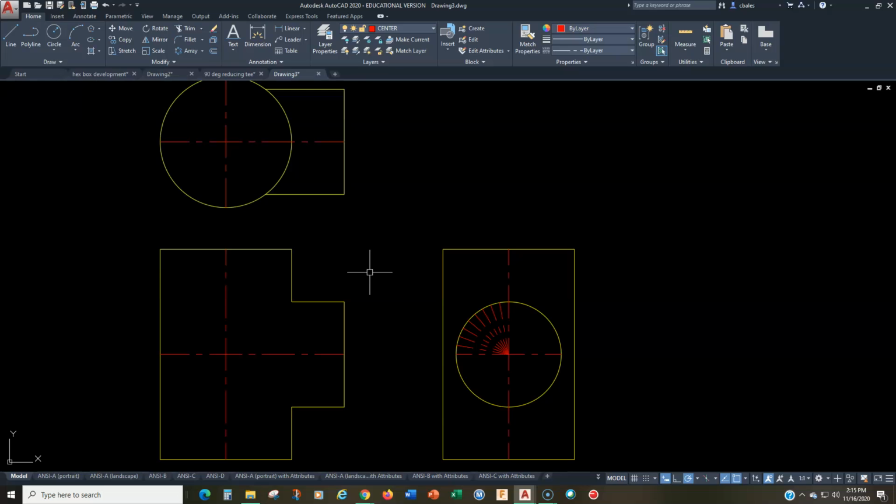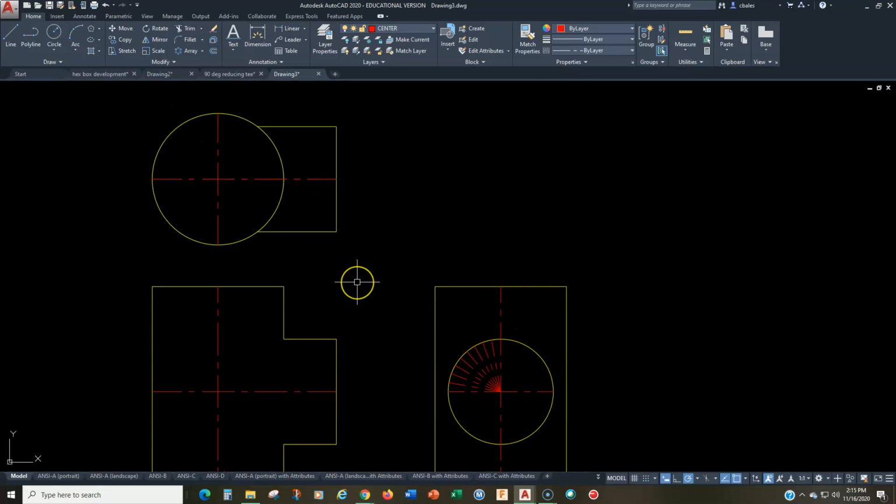Okay, so now watch. This is where we kind of project these across. Now, what I want to do is I want to project this up and over into this view and then down, and we're basically going to create a loop. In order to help us do that, we have to draw something called a miter line. And a miter, M-I-T-E-R, is a line that helps us reflect common edges between the right side view and the top view. Okay? So in order to find my miter line, I need to project 2 points that I know coincide with each other. And that's going to be this point up here and this point over there.